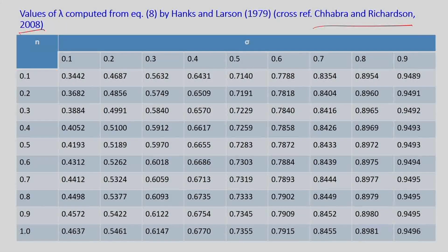Okay. Now, if in place of power law fluids we have viscoplastic fluids, either Bingham plastic or Herschel-Bulkley fluids, things become more and more complicated, because even for a single pipe flow, for velocity there are two profiles in the case of viscoplastic fluids, that is the plug-like region and the deforming fluid-like region. So in the concentric annular region those things become even more complicated.